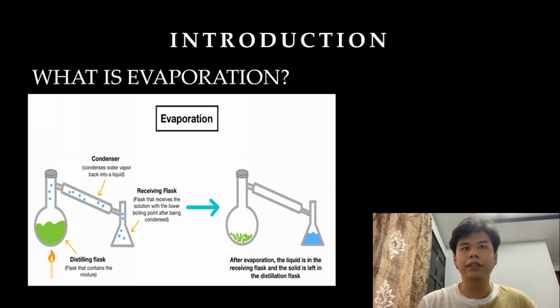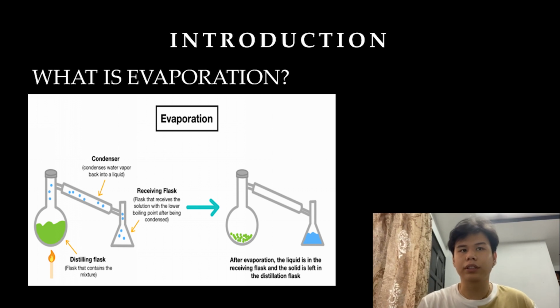The underlying principle behind evaporation is that in order to change its state, the matter must either gain or lose energy. In the case of change of phase from liquid to gas, molecules of matter require energy to overcome their potential energy by their kinetic energy. Evaporation is an operation used to remove a liquid from a solution, suspension or emulsion by boiling off some of the liquid. It is thus a thermal separation or thermal concentration process.